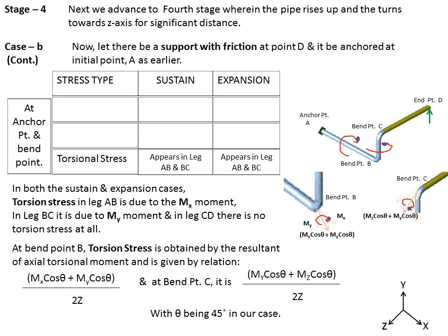Herein we saw how the component stresses of the ASME B31.3 code equation appeared in various systems and how they were calculated. Once we know the root cause of their appearance and the calculation factors, we can easily optimize and control our stresses in any of the complex configurations. Optimization of stresses is necessary, as we have seen that the more restraint we provide, the more the sustained condition is stress relieved, while the expansion condition gets more stressed. So with the supports, we have less sustained stresses, more expansion stresses. So this optimization is very much necessary.